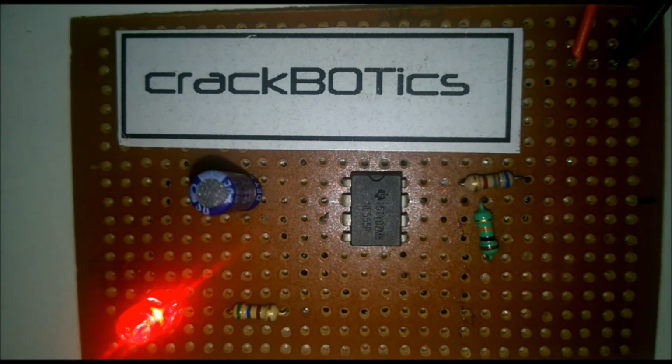It's quite easy to get confused about where to start. For example, this IC 555 has 8 pins in total. Whenever you name the pins, always make sure that you start from the notch. As you can see in this video, there is a notch which is facing towards the north. You have to start from that terminal, counting 1, 2, 3, 4 and so on. So this is how you have to name the terminals, starting from the notch.